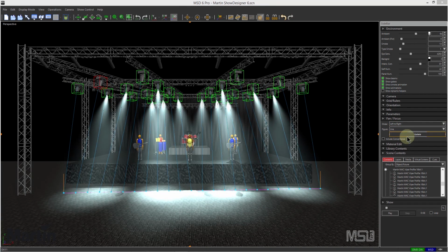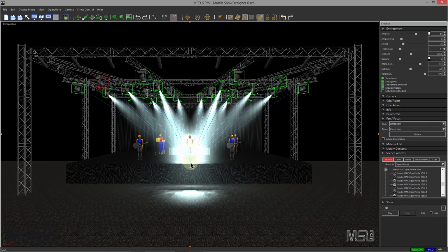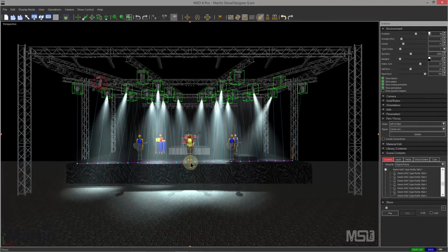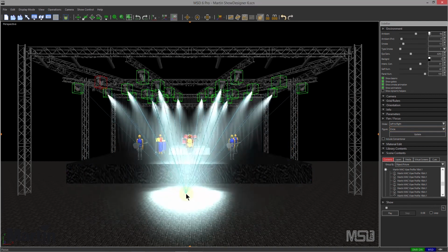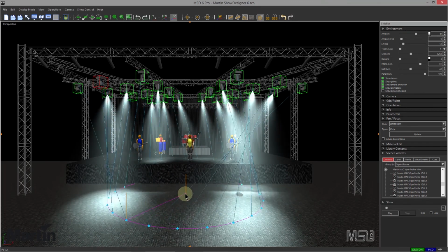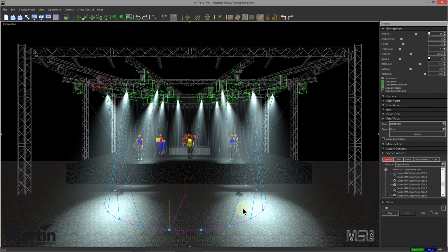If MPC was running at the same time, these values will be sent to MPC and could be recorded into a preset or a cube. So you can do a line, you can do a center line, which means that it's going to start from the central point. You double click, and then as you drag, the fixtures will spread from the center. The other mode is the circle. So let's click here and we'll double click, and as you move, you get a circle, and then you can rotate that circle just by moving the mouse. It doesn't matter how many fixtures you have, it could be different types at the same time. You can do circle and lines.